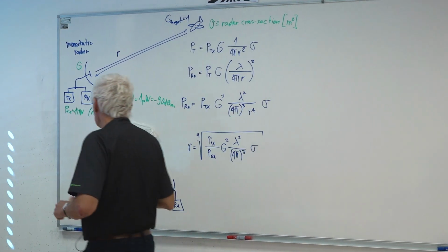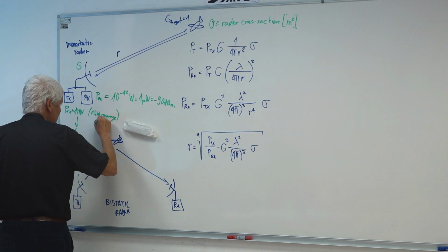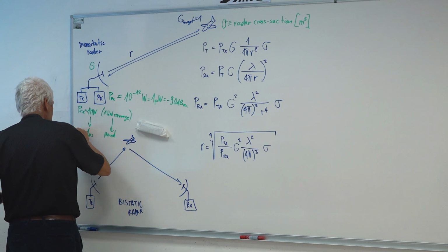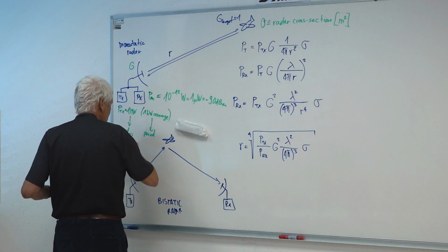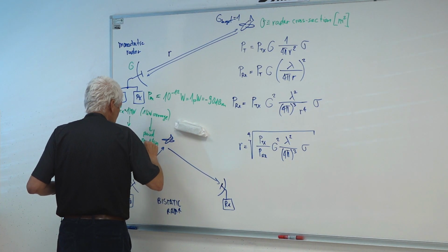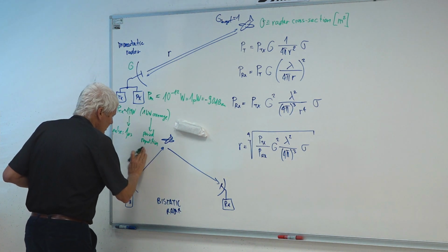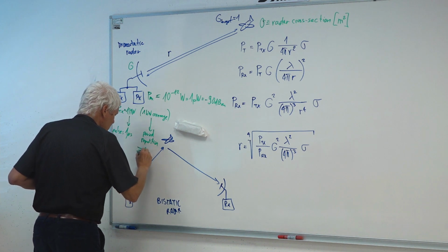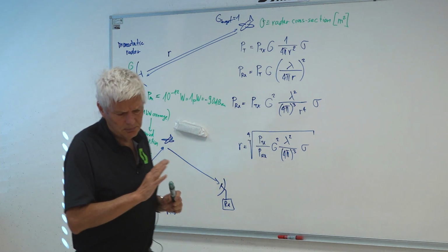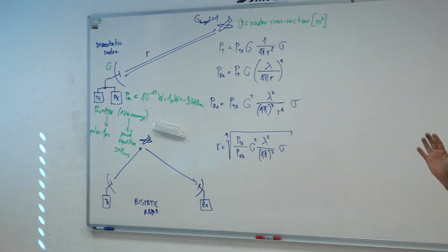So this is the P transmitter. 1 megawatt is transmitted for 1 microsecond, and the repetition period is usually more than 1 millisecond. That's where the 1 kilowatt average power comes from. This is not a particularly powerful transmitter for a radar: 1 megawatt peak, 1 kilowatt average.